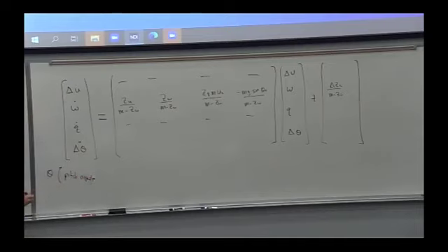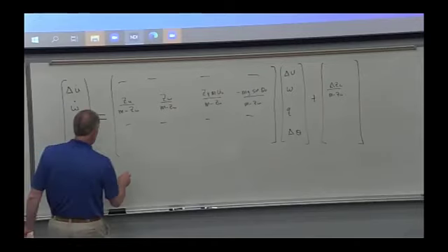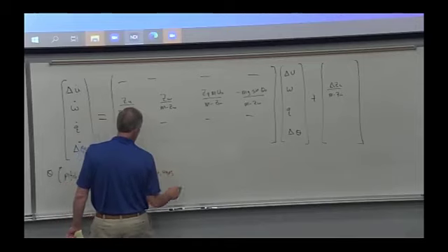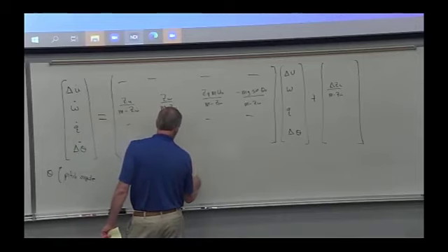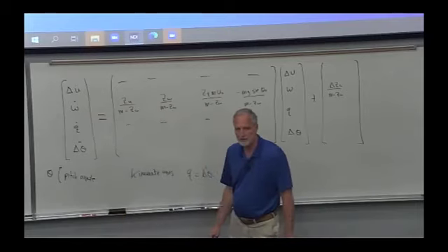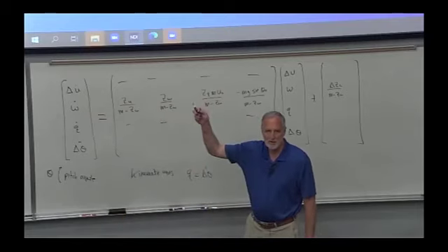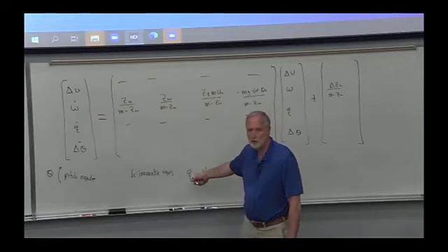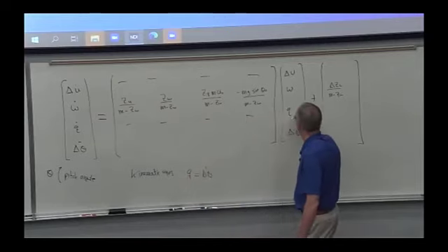Yeah, so delta theta dot is related to the pitch acceleration, right? Or actually the pitch rate. So there's an equation from the kinematic equations that says that Q is delta theta dot. And it makes total sense because theta is the pitch angle. And so what's the derivative of pitch angle? It's pitch rate, which is what we call Q. And that's already in our equations.